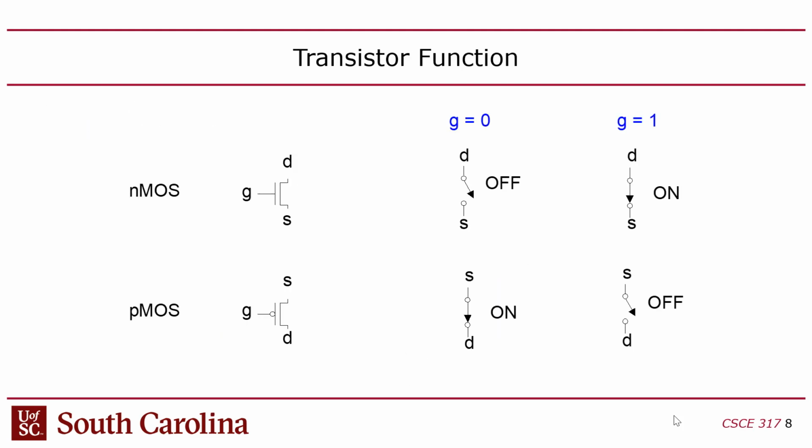Okay, so we talked about that. So NMOS and PMOS is basically the gate controls whether the transistor is on or off. If it's on, drain and source have a low resistance. If they're off, the drain and source have a high resistance. We talked about that even back when we were talking about SPI and the push-pull driver. It's the same thing as the push-pull driver discussion.